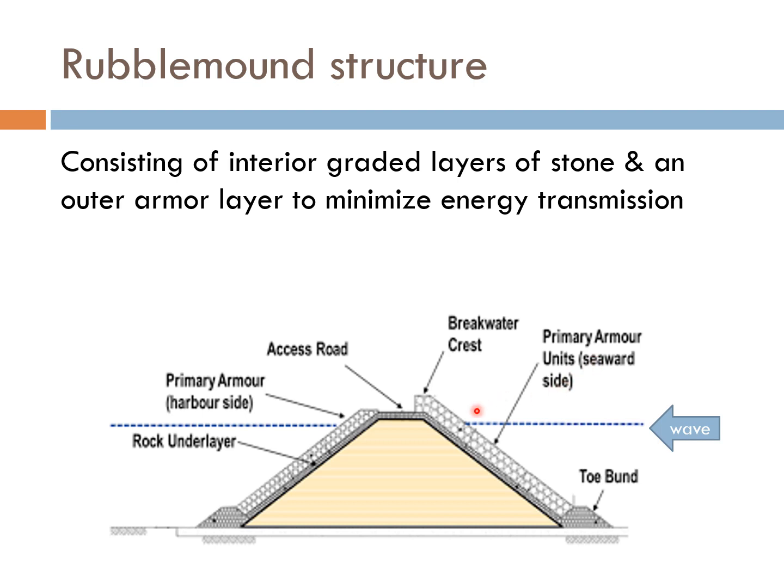Notice also that the crown level on the seaside is higher in order to avoid overtopping if necessary. And at the toe, protection is provided to avoid scouring and toe failure. The crest usually will be designed wide enough for maintenance machinery access.